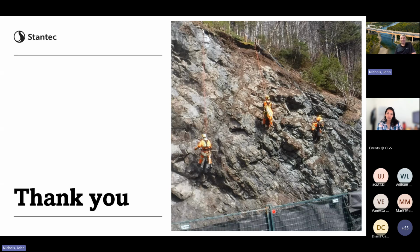I will say that for shotcrete testing, you shoot a test panel, core that test panel, and test each batch you do. One thing about shotcrete, if you've never used it, is that you need a very skilled nozzle person, and it's complicated to apply behind a welded wire mesh. So I think the strength was 50 MPa. What was the second part of that question? Energy absorption rate for shotcrete? I'm not sure about that. I'd have to look that up.